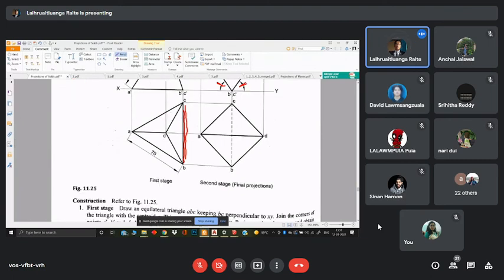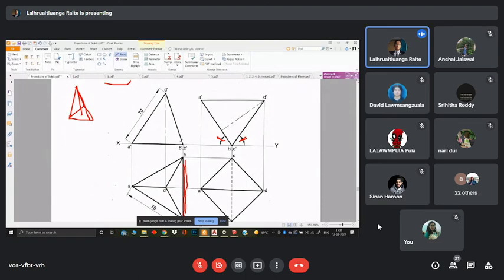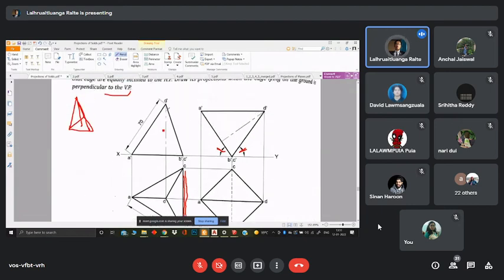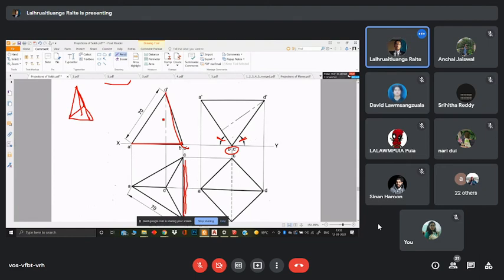All right. So here we get the front view. As we are looking at it from here, we are simply seeing a triangle over here. And then we rotate that, making sure that BC is here. And when we rotate it, we make sure that the angle made by the line ABC and the line DBC is equal. Because this is already distorted, you have to calculate this internal angle that you have formed yourself, the angle that you have formed over here, as well as this over here.